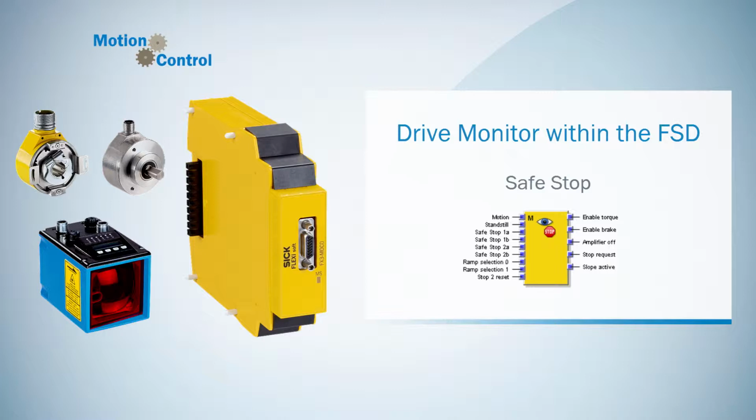Now we go over to the outputs. With the outputs Enable Torque, Enable Brake, Amplifier Off and Stop Request, the drive system can be controlled. Enable Torque switches off the torque of the drive system. Enable Brake switches off the power supply to the mechanical brake. Amplifier Off triggers the shutdown of the amplifier, the drive's torque, and also engages the brake. And Stop Request triggers the stop ramp of the drive.